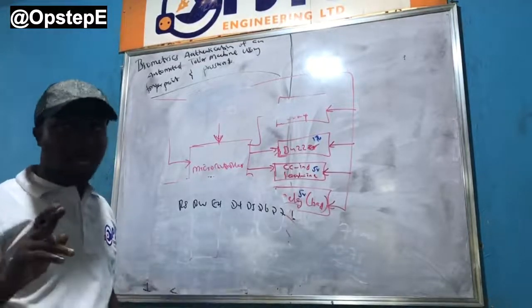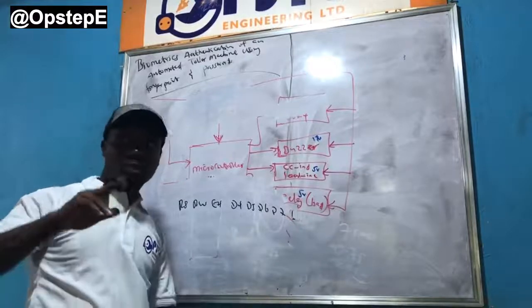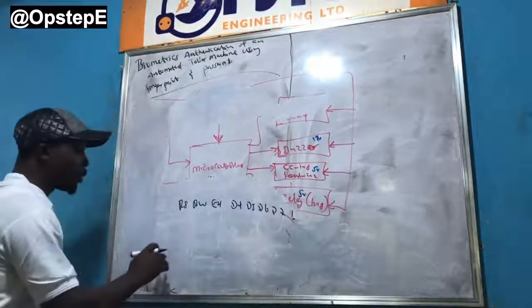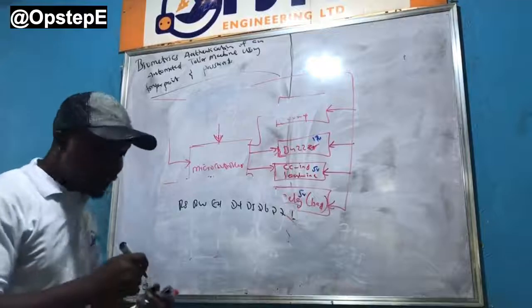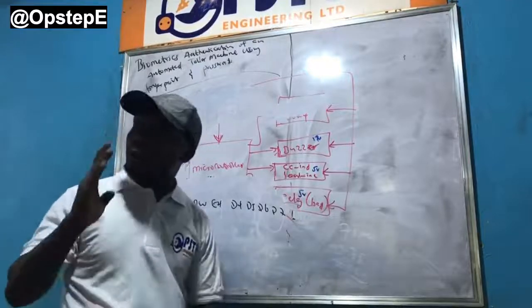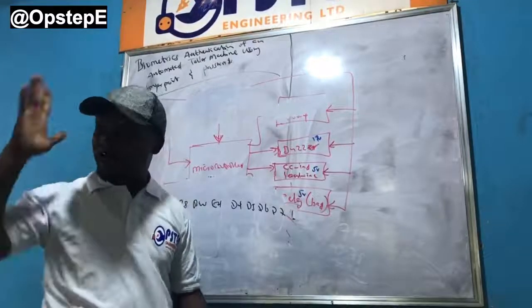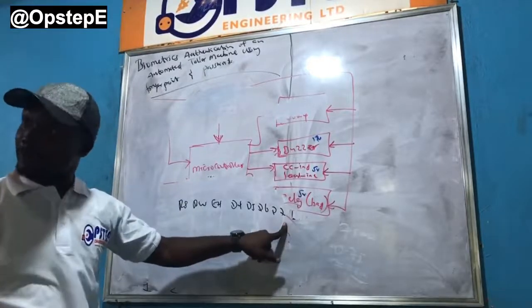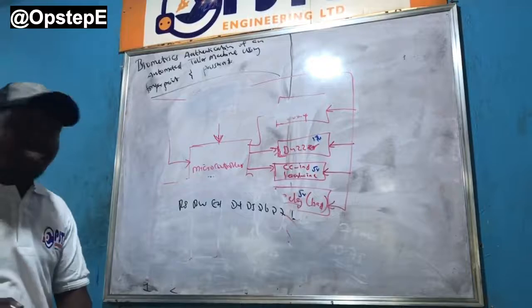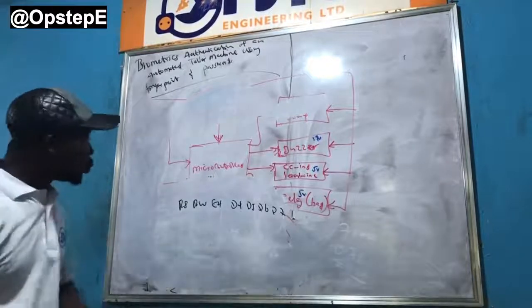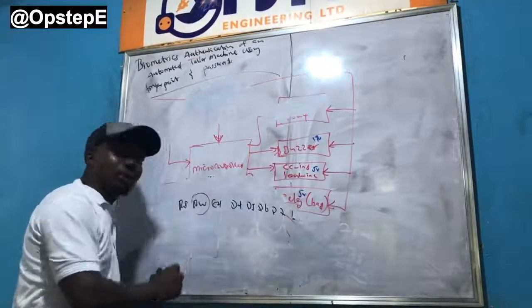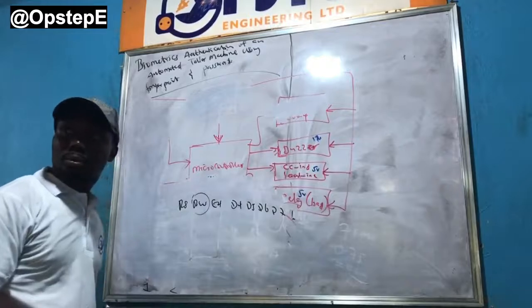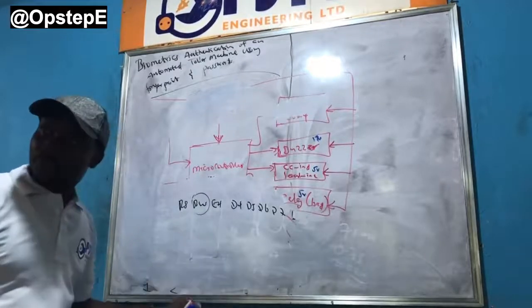But pay attention. Now I don't think I'm supposed to tell you this. You're supposed to know. Please look. Port A itself can only offer you what? 6 input output pins. And this LCD requires what? 7. So what that means is that in your LCD configuration, you are going to get rid of your RW. But you need to tell it in software, otherwise it's not going to work.